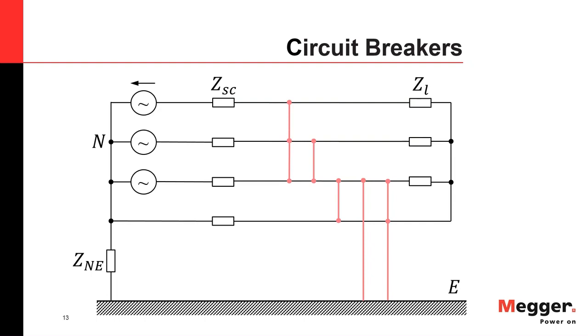That is quite a rare fault, as I will show you in a second, but it can happen and is the most severe. Then you have a line-to-line or phase-to-phase fault. And then all the other faults are pretty much single-phase faults, where one of the phases is touching the Earth or the neutral or both. There's also the scenario where you could have a phase-to-phase fault that then goes to ground. The difference between these faults is pretty much just the grounding scheme of your network, which determines what faults can develop and what is not so likely to happen.